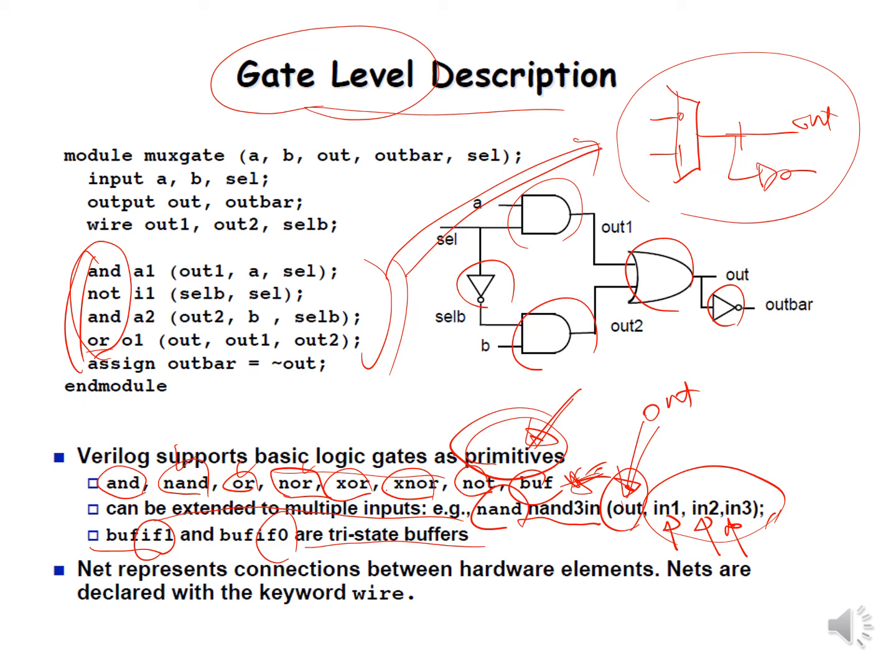The node and net names, with capital and small letters generated in one CAD tool, are recognized by that tool, but some other tools cannot recognize those cases. Sometimes that causes errors in the actual simulation. So the only time you see this gate level description is mostly when you debug your design from the synthesis tool.